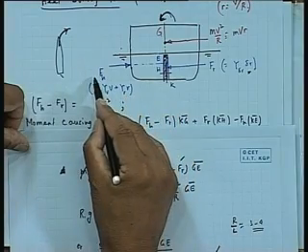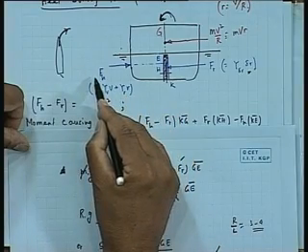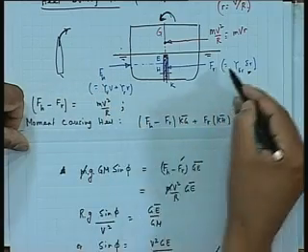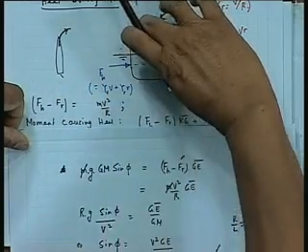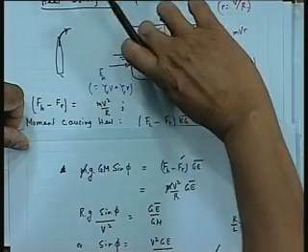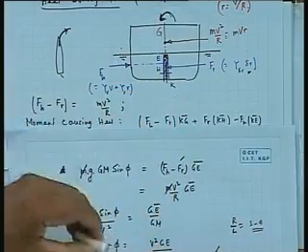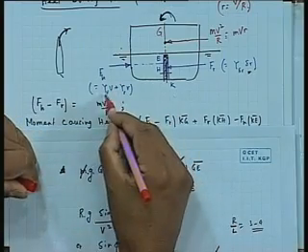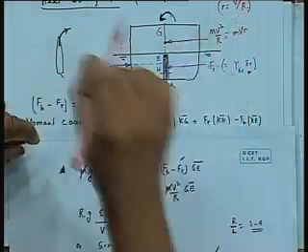In fact, an interesting point that I want to tell you also is the initial phase. If you remember the first phase of the turn, as soon as you put the rudder up, this reaction force is actually small. So you have given a rudder force but no reaction force. So at that time the ship turns inward. So in the initial phase the ship turns inward and then the reaction force becomes the acceleration force. If you recall, the reaction force was Yv dot v dot because in the first phase we had only v dot and r dot, no v and r. So initially when you put the rudder, I immediately have the rudder force, but not the reaction force. What happened? The ship has actually turned inside. So as soon as you put rudder, the ship turns this side, then it begins to turn this side.